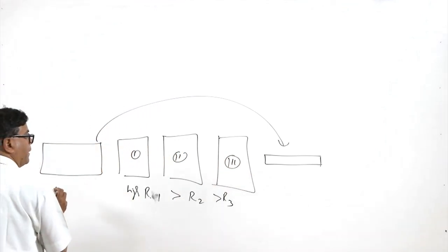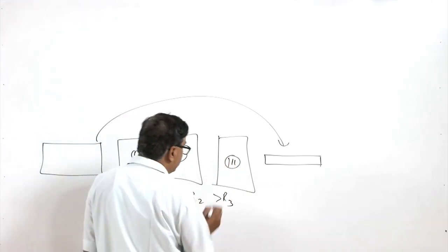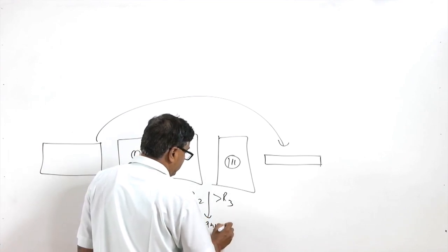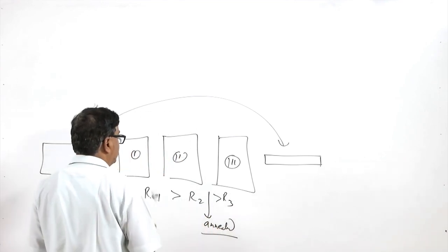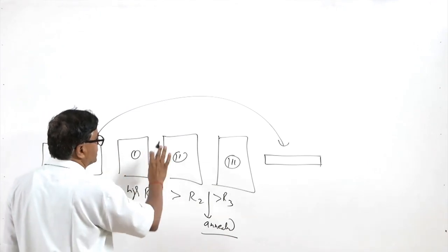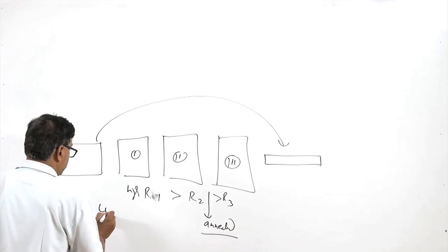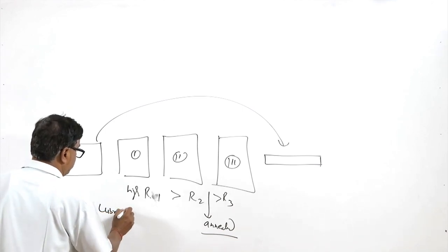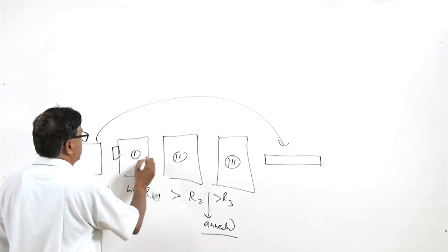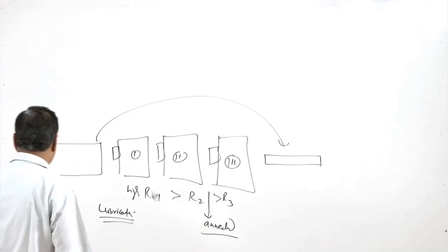Sometimes, if the material is work hardened too much, then in between the stages the material may be annealed in order to restore the ductility. In addition to drawing through the different stages, what we need is lubrication. Before each stage of drawing, lubrication is done of the wire or the bar which is to be drawn.